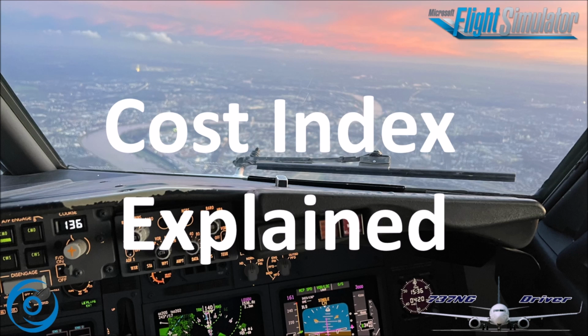So generally, the cost index is the equation time cost in dollars per hour divided by fuel cost in cents per pound. Note that some different manufacturers may be using different units here, but in general it is time cost divided by fuel cost.